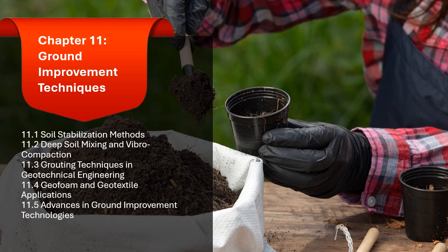1.5.3.1 Energy efficient ground freezing systems. Innovative ground freezing systems now use more energy-efficient refrigeration methods, reducing the overall carbon footprint of the process. Additionally, the use of liquid nitrogen and carbon dioxide has improved the speed at which freezing can be achieved, making it a more viable solution for urban projects or areas with sensitive ecosystems.